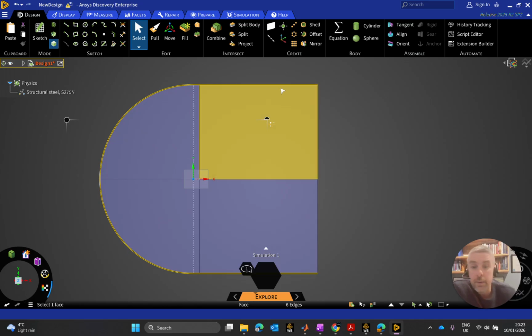Why not make it a wall? Well, you can. Absolutely, you can make that a wall if you want, but the only effect is that if there is any sort of physics happening up here, or any effect of the airfoil way up here, even though it's 15 chord lengths up, what you will do is you'll start to get wall effects up there as well, which could adversely affect your flow field in here, which can have a knock-on effect here, and eventually they will resolve to some sort of a steady state.